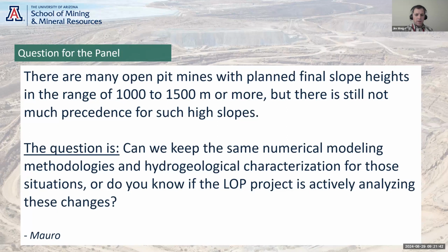It's also opened up something we hadn't really thought of, and we're actually next year going to put in a number of wells to depressurize ahead of our next slice coming down. So we're going to drive the wells deeper below the current mine bench and down into where the existing slope's going to end up. So do some pre-depressurization mid-slope with one of these wider catch benches. Go ahead, Travis.